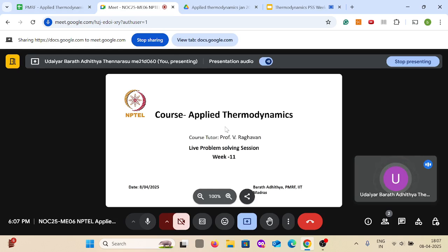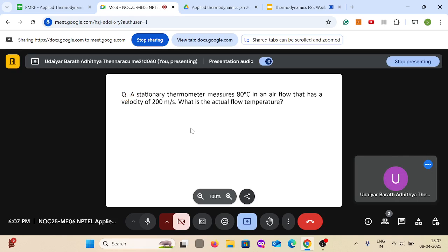So that's what happens in a normal shock, and we'll see some problems on this. Your velocity in this case will be reduced, and since velocity is reducing, your pressure will increase and your temperature will also increase. So this all happens when a flow goes across a normal shock. We'll see some problems on those. So with that, we'll start some problems.